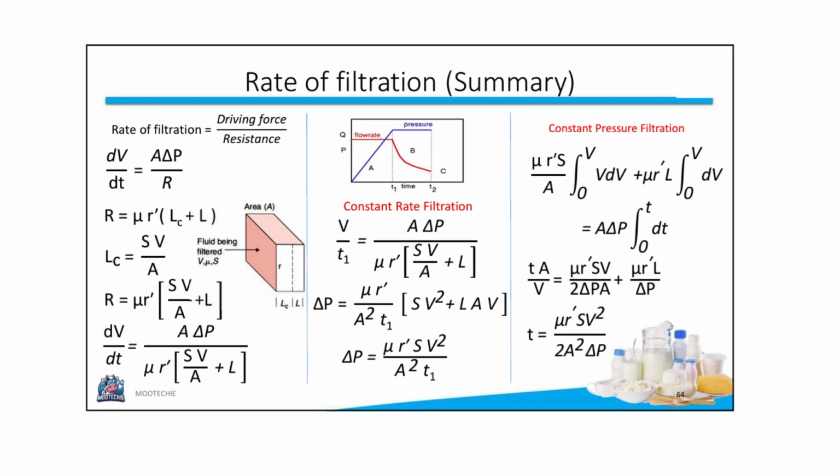To summarize the theory, the rate is driving force over resistance. The resistance depends on viscosity, specific resistance, and the combined thickness of the cake and medium. The governing equation combines all these factors. We have specific integrated forms for both constant rate and constant pressure filtration scenarios.